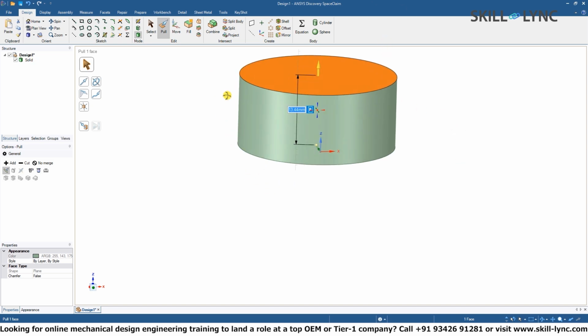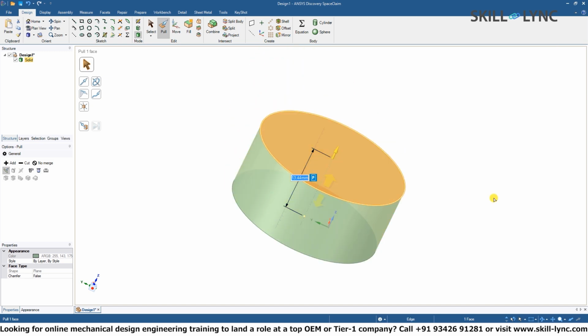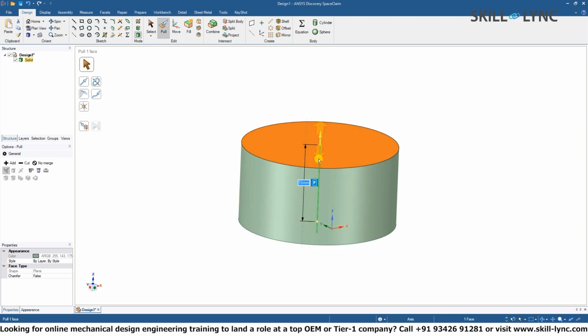So this is how we can simply create some 3D geometry from a 2D sketch. As is similar with 2D geometry, you can set the different parameters that you wish, such as the depth of the cylinder. If you want it to be 15 millimeters high, you can just type that in, click enter, and it will automatically adjust the figure to suit your needs.